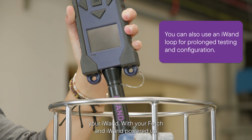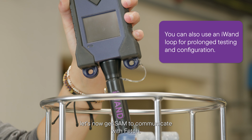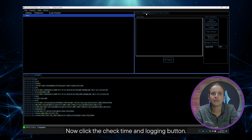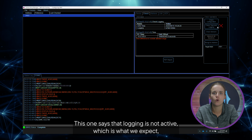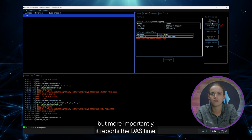With your fetch and iWand powered up, and with iWand's antenna touching the fetch transducer, let's now get SAM to communicate with fetch. Click on your fetch's address, and then click on the Check tab. Now click the Check Time and Logging button. We will then see the status of the instrument. This one says that logging is not active, which is what we expect. But more importantly, it reports the DAS time.